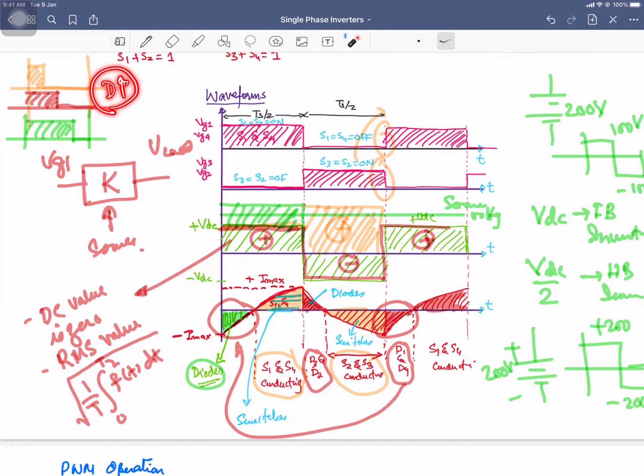So if you increase the duty cycle of this pulse, because we are going to convert it into that one, instead of applying the constant voltage, we are going to apply a train of pulses, right, a PWM signal. So once you change the duty cycle of these gate signals, the area covered by the gate voltage will change, and at the same time the output voltage will change.